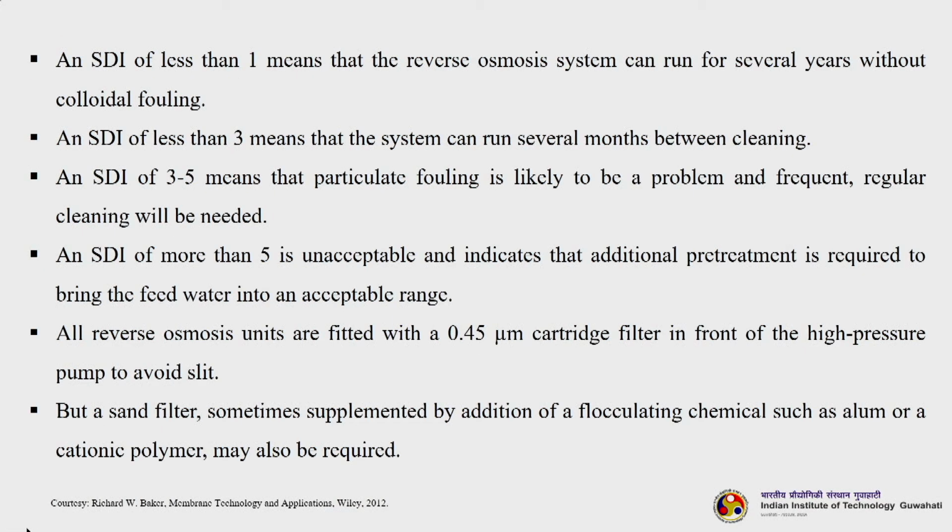An SDI of less than 1 means the reverse osmosis system can run for several years without colloidal fouling. So, an SDI of less than 1 is usually better and recommended. An SDI of less than 3 means the system can run several months between cleanings, and an SDI of 3 to 5 means that particulate fouling is likely to be a problem and frequent, regular cleaning will be needed. So, now you understand the importance of SDI and why we should measure it. An SDI of more than 5 is unacceptable and indicates that additional pretreatment is required to bring the feed water into an acceptable range.